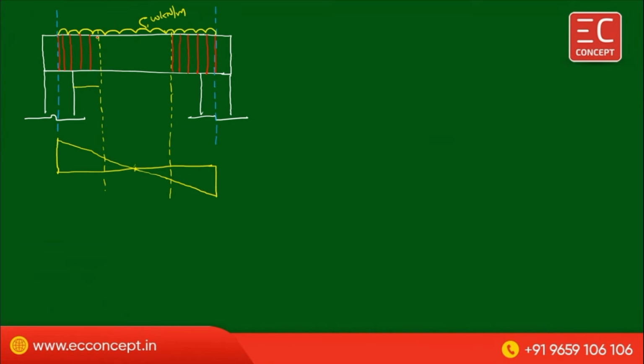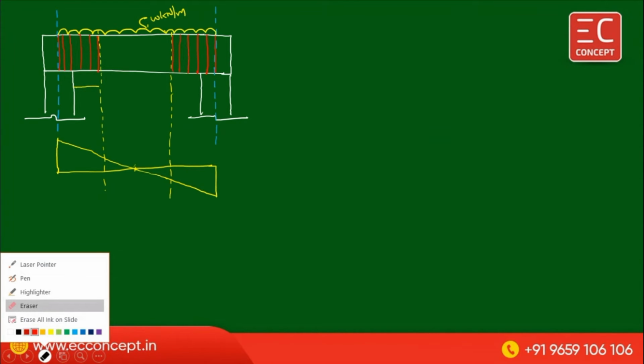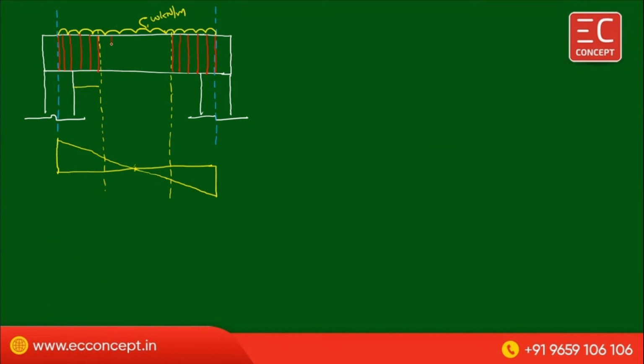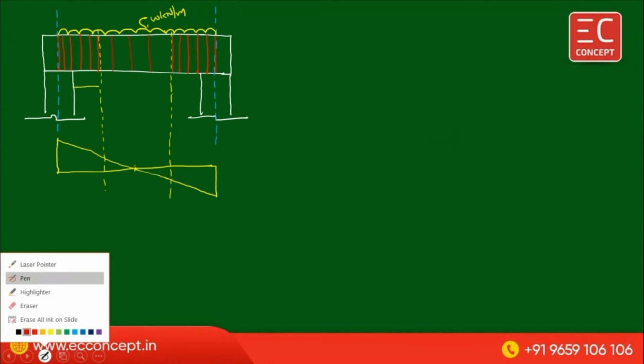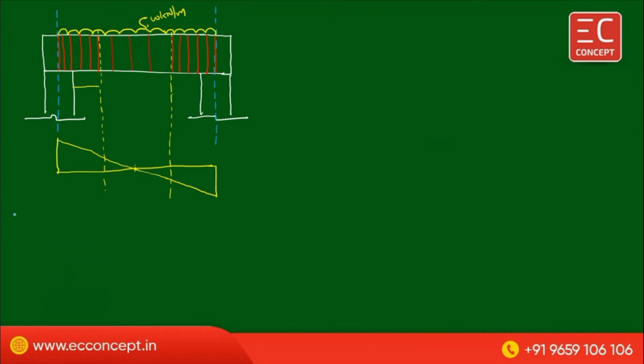After that, you can use the stirrups at somewhat higher spacing. Why? This is not a critical section. The shear force is anyhow less. But the spacing will depend upon the shear force.